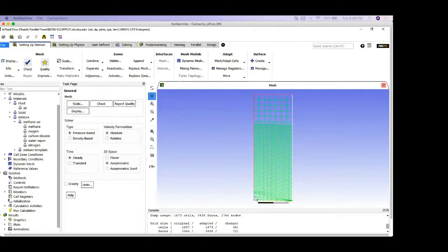What does my oxygen profile look like through the flame? It's an initial guess. So I'm going to mark the regions for that so that I can specify the initial guesses in different regions. In our fuel, we have the initial fuel inlet, mixture inlet region, where no combustion happens and it's just the mixture mixing and flowing across. And then we have the flame zone, and then the post flame zone. So I'm going to define 4 regions because we also have the sheath flow on the side.